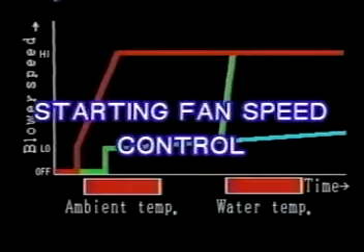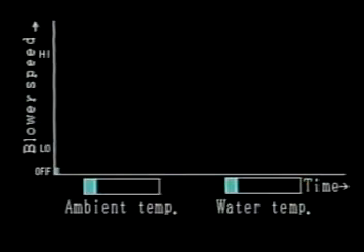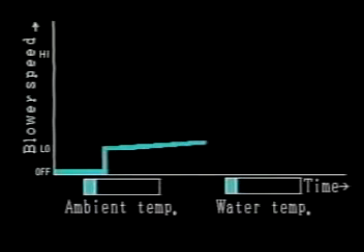The automatic amplifier operates the starting of the fan speed control depending on the air outlet position, the engine water temperature, and the ambient temperature. When starting the system with the engine cold, with the air outlet position in any position other than vent, and an ambient temperature below 59 degrees Fahrenheit, the blower will remain off for a maximum of 90 seconds.